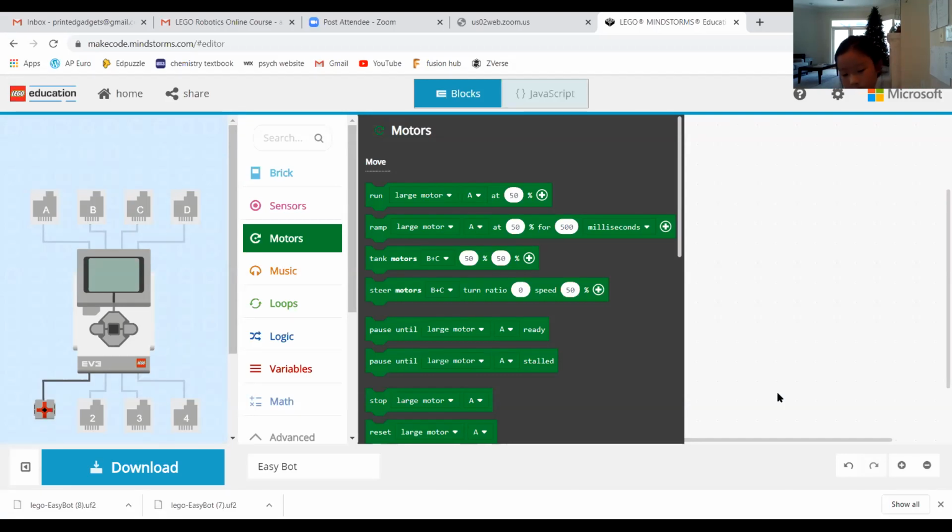Yeah. All right, so if your EV3 is showing a blank screen, that means your program is running. So which program are you playing? Is it the one with the touch sensor? All right, so try pressing the touch sensor. I don't think you activated yours, and then it should move. The ports where you connected the touch sensor may be different, so check with your program.